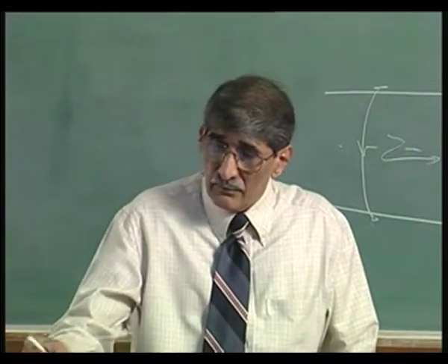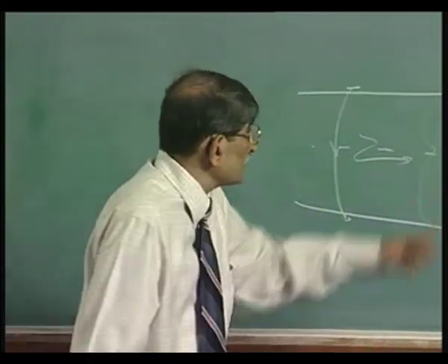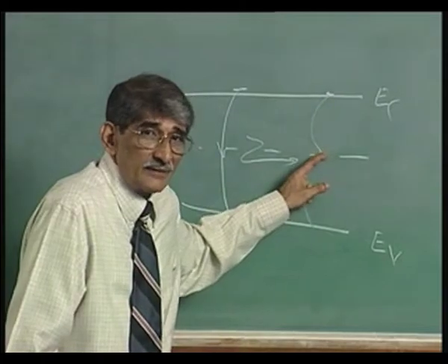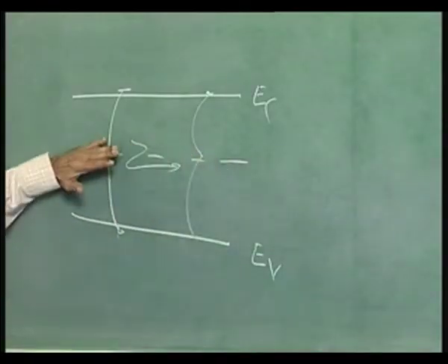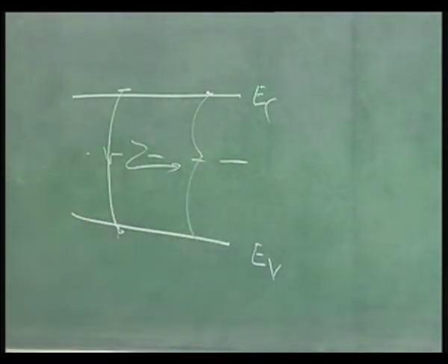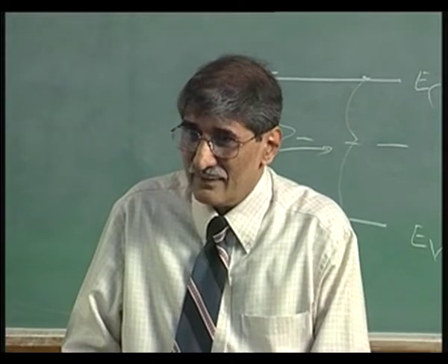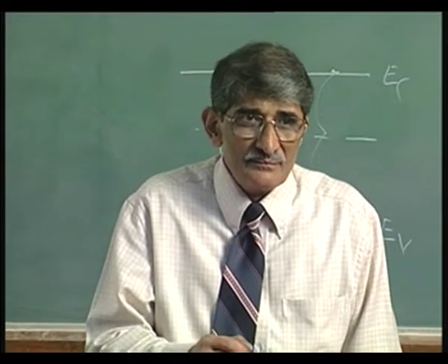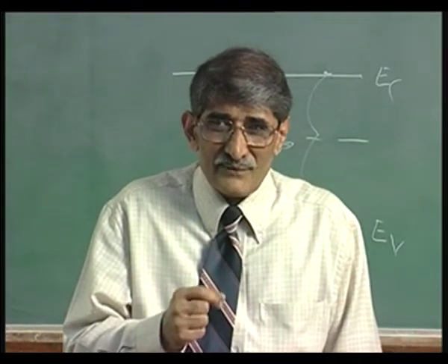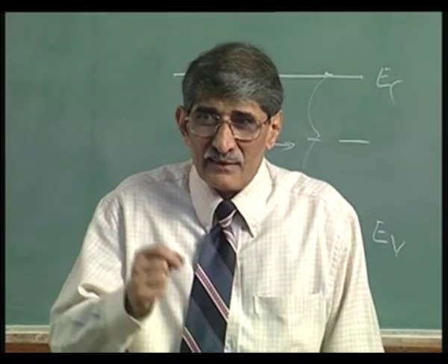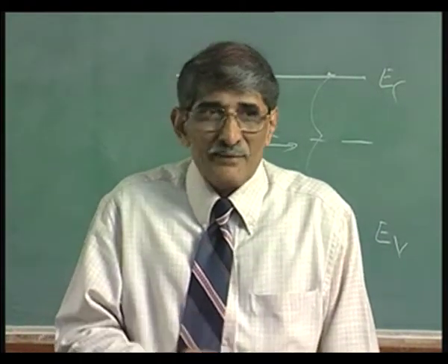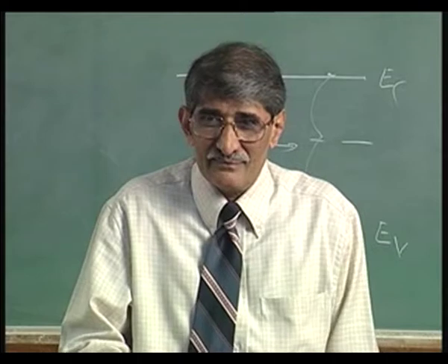Now, with liquid phase epitaxy, this is a very important thing to note down, these levels are absent. All those deep impurities do not go into the solid when the temperature is low. Here a metallurgical term is used, segregation coefficient.